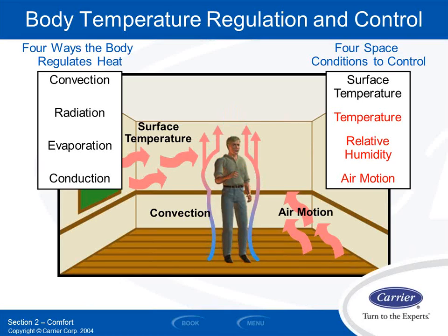I can't control the relative humidity. A lot of systems don't actively do that, but it's pretty easy to do with lots of systems. And you should start thinking about ways to control the humidity to some degree, like I said, by forcing cooling on and slowing down the blower and stuff like that.